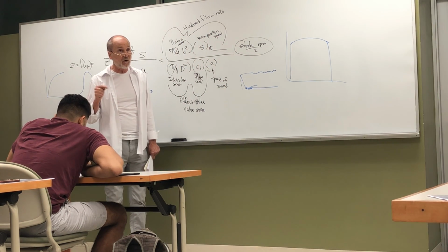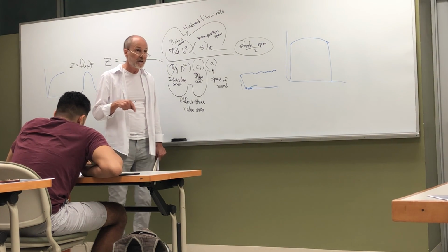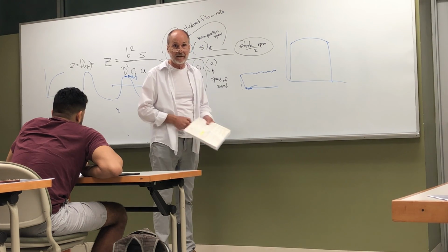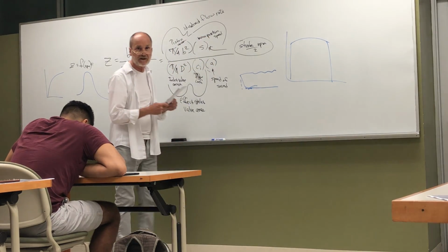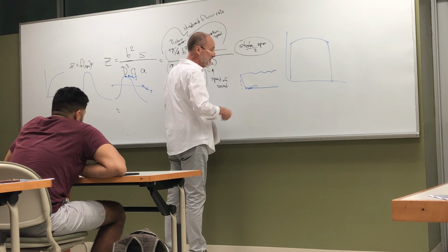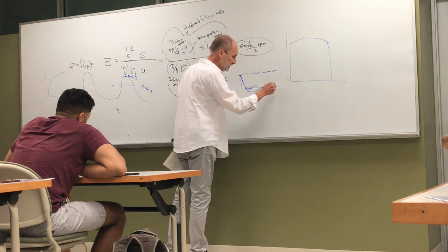That's because at a very low RPM, and Mach index 0.2 has to be a very low RPM, the pressure drop across the valve is becoming negligible. So we're approaching our idealized case. As we go to higher and higher Mach index numbers, we have less and less time to get from here to here, and so we begin to have to go like this.